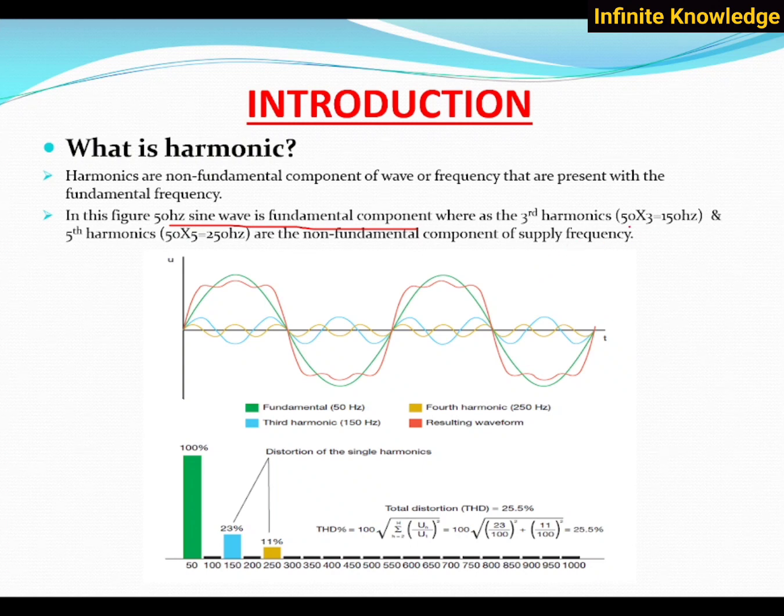You might be aware of what a non-linear load is. Non-linear load means a power electronics load, like semiconductor devices, like GTOs, MOSFETs, transistors, rectifiers. What is the non-linear load doing? You are aware of SCRs. What do SCRs do? There is only a gate pulse. When the gate pulse is applied, it conducts and the current flows from this direction to this direction.